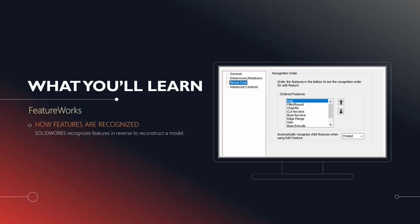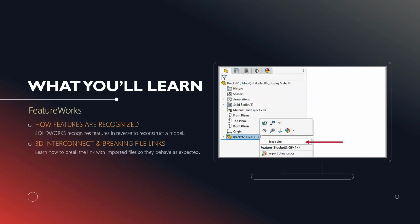So in order to break down a model, deconstruct it, SOLIDWORKS works in reverse order to recognize features, opposite from how you would typically build them. So it's going to recognize things like fillets and chamfers first, and then do primary boss extrudes last. We're going to look at 3D Interconnect settings and breaking file links.